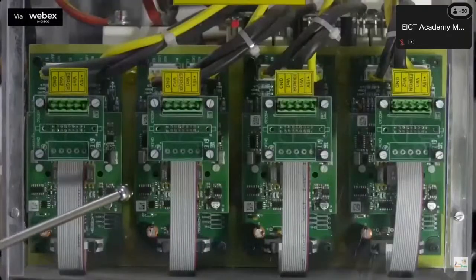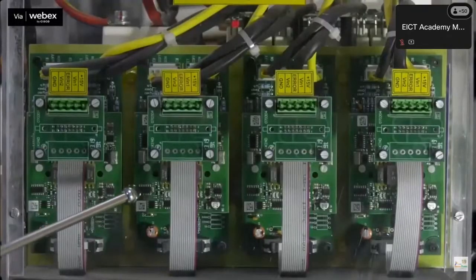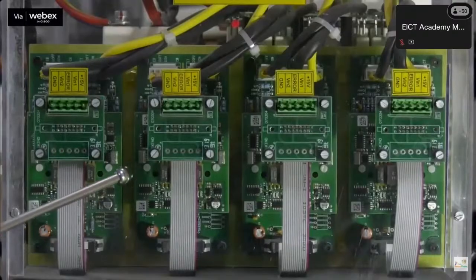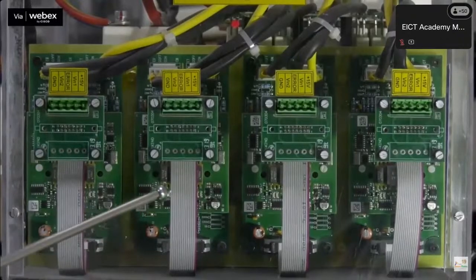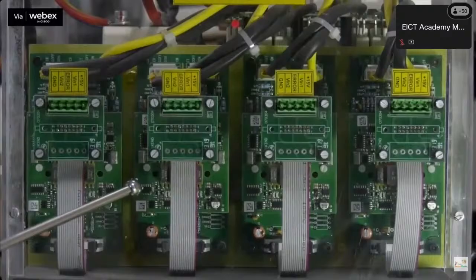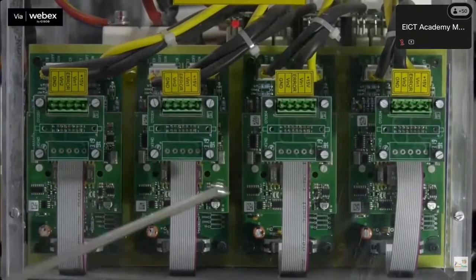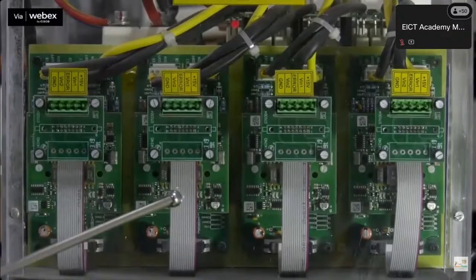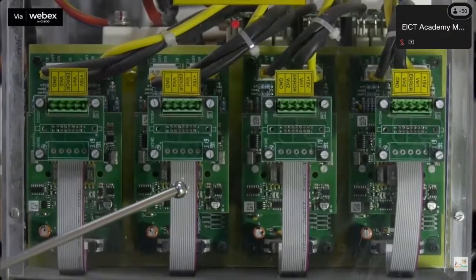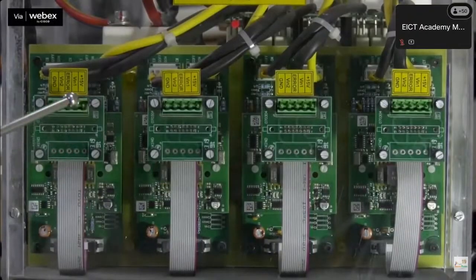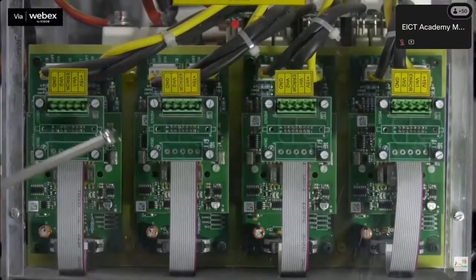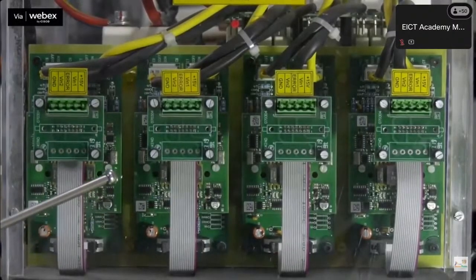To trigger the IGBT switches, gate drivers are required to convey the pulses received from the controller to the gate terminal of the IGBT. Each driver can trigger one module. Hence, four Skyper 32R gate drivers are provided. And these drivers also require an isolated DC input of plus or minus 15 volt to operate. Moreover, these drivers have inbuilt dead band protection as well.